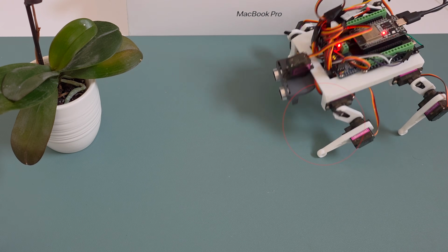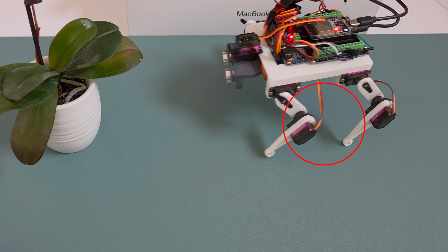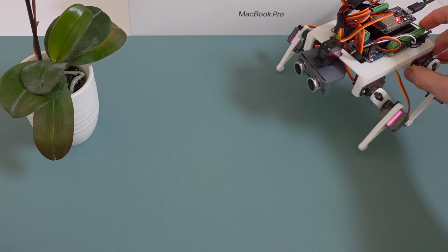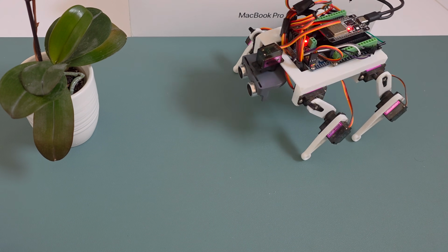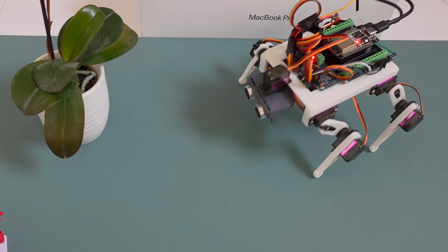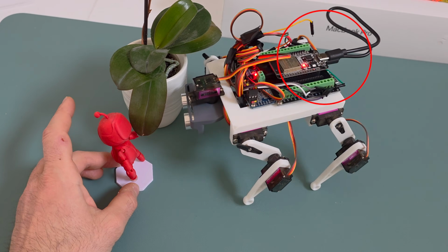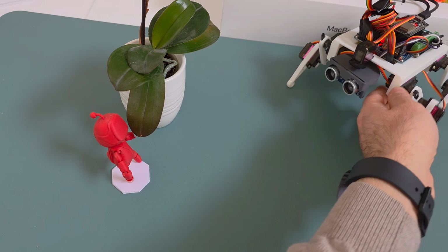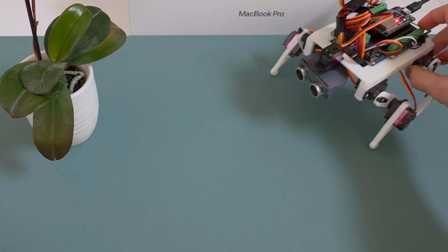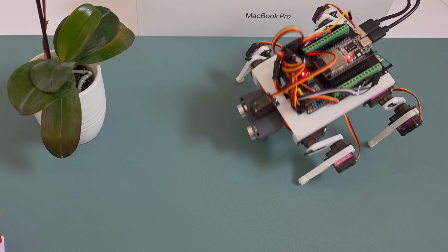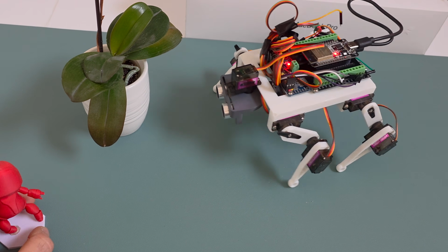During testing, the legs were incredibly unstable, twitching and causing the ESP32 to reset every time Albert tried to take a step. At first, I thought it was my code, but then I realized the problem was hardware interference. The servos and the ESP32 were sharing the same power line. When the 8 servos kicked in, they created a massive voltage drop and electrical noise that choked the microcontroller.